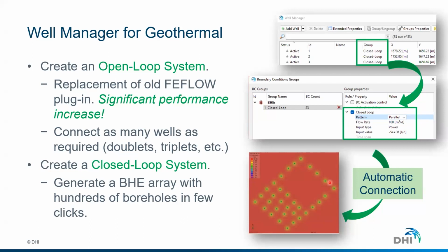For the case of the closed loop system, this was needed due to the high demand from FEFLOW users, especially in Europe, working with borehole heat exchangers. There was the typical limitation of working with hundreds or even more borehole heat exchangers, which have to be interconnected. The interface of FEFLOW has allowed you to create borehole heat exchangers since probably before version 6.2, so even in version 5 it was possible to implement that. But there were no significant tools to connect them.